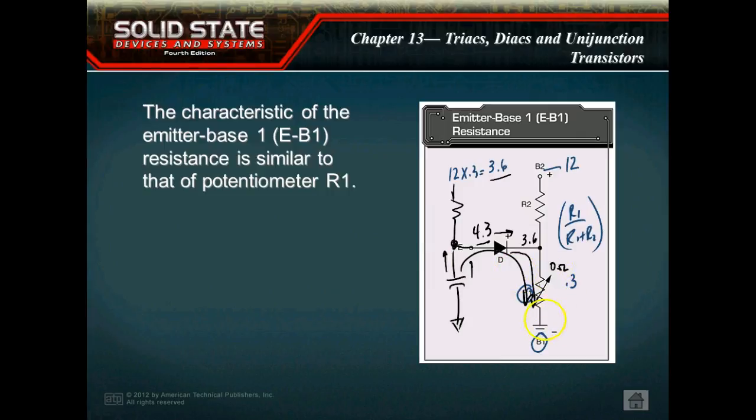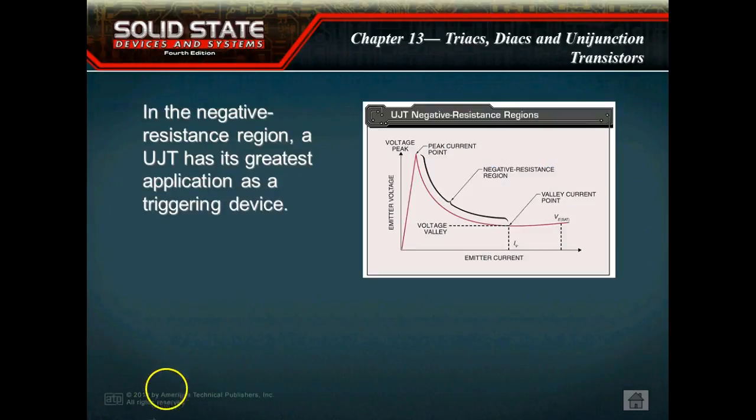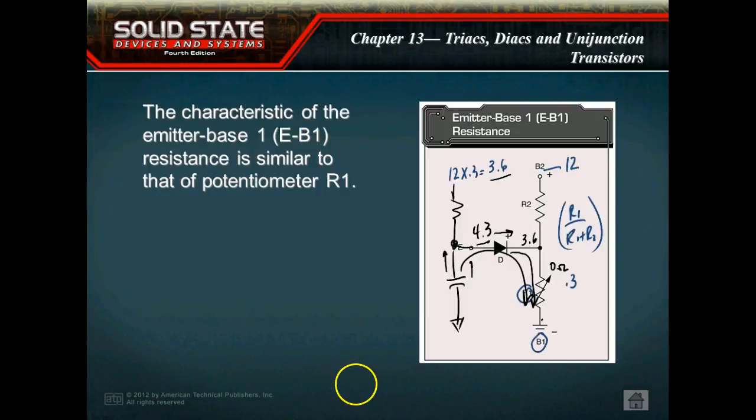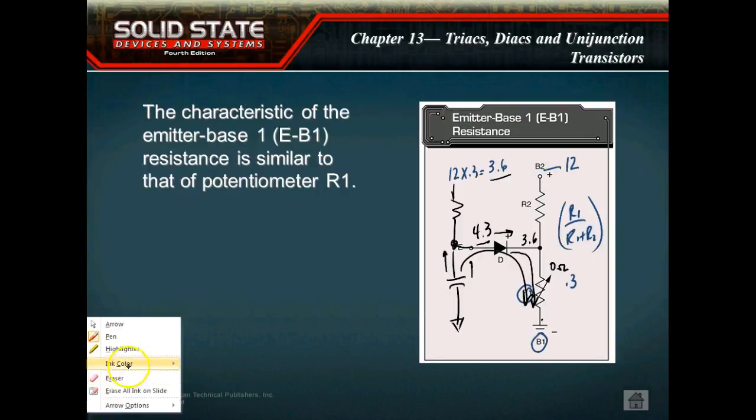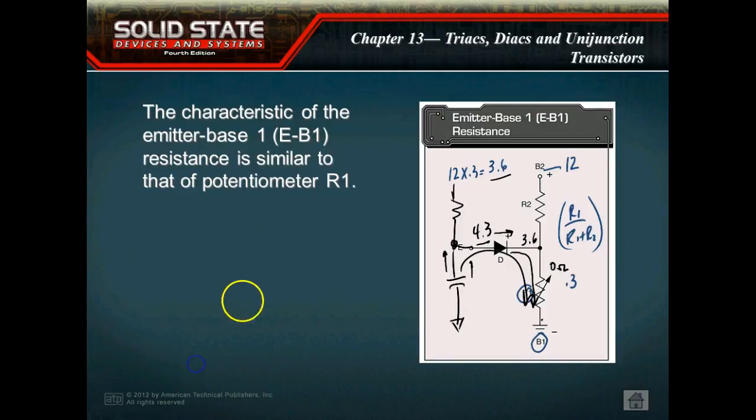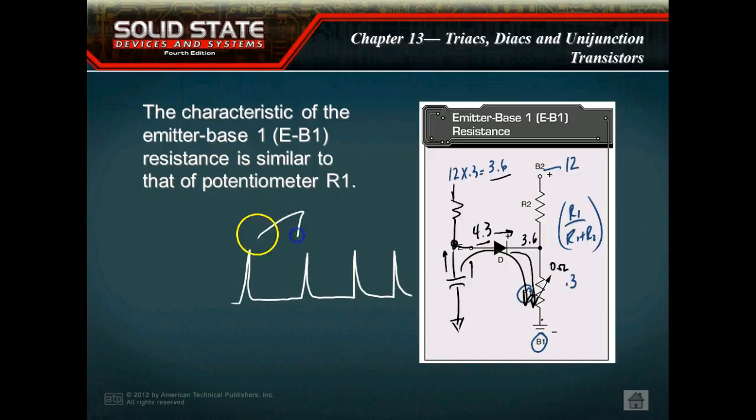So if I was looking across my load, if I had it down here, we would get a signal that looks like this. We set that with the ratio of this resistor and this capacitor. So we use these guys for oscillators.